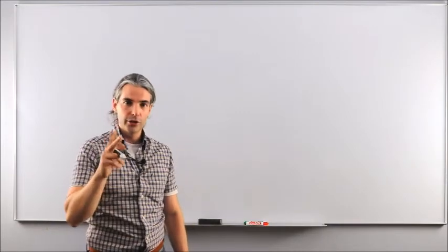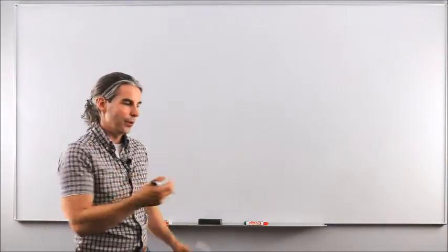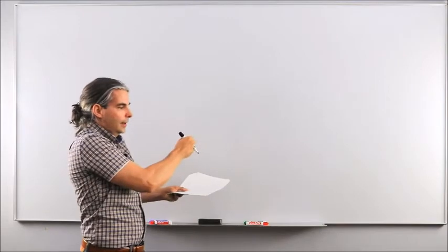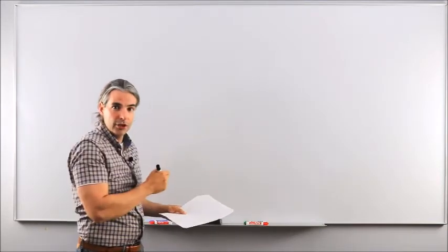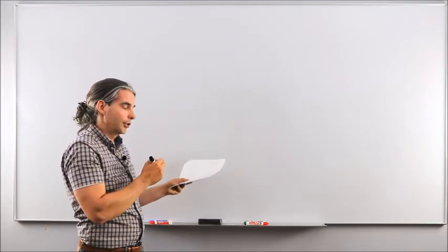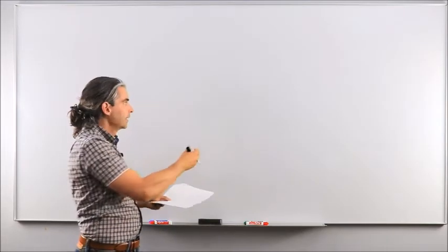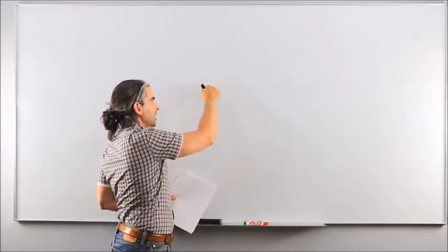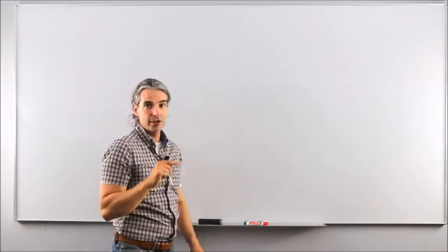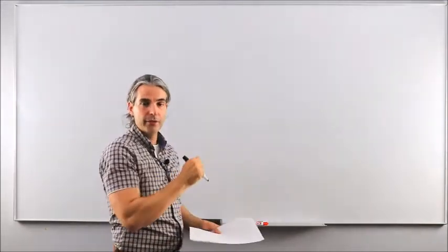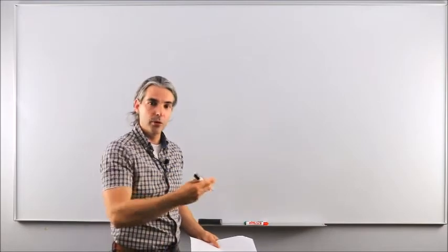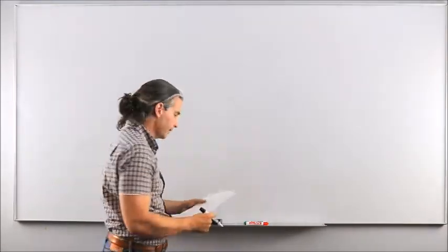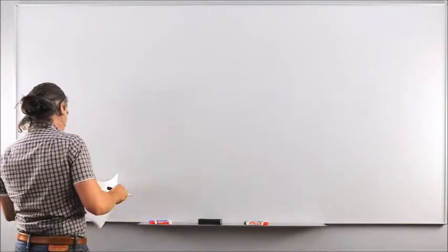So those 2 conditions will ensure that we bend our root locus exactly in a way to make sure that it passes through the desired pole location. And the magnitude condition will ensure that we're going to stop the poles exactly at the right bus stop along the new paths we have defined to ultimately obtain the desired pole locations in a complex plane. All right.